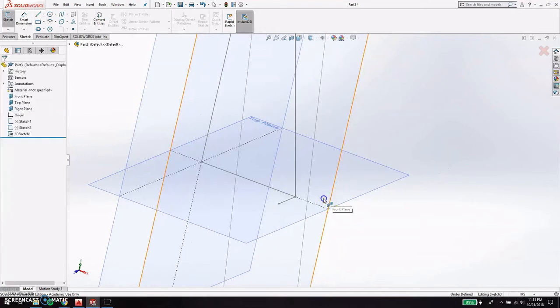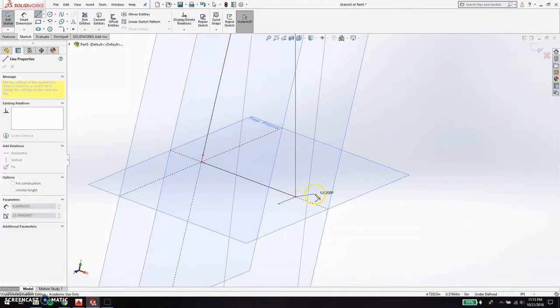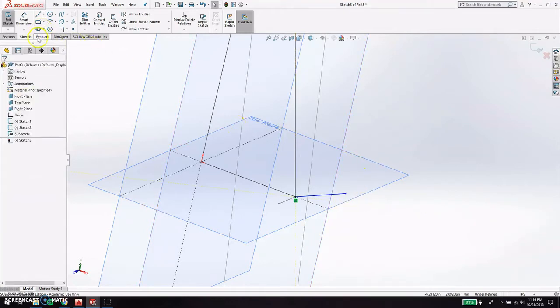And so as you can see, it's already getting a little frantic here. So you can see it's not easy for me to get it perpendicular, but nicely I can do smart dimension, and I can angularly make it so that it's 90 degrees with this line up here, and that'll do the trick for me. So I'm going to draw this, and then I'm going to go into smart dimension. I'm actually not going to do this little tab.